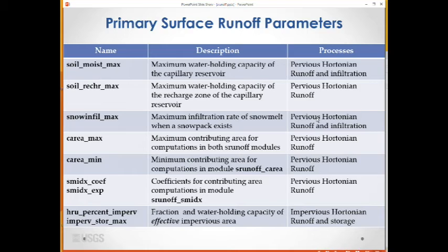Parking lots, roads, sidewalks, and building roofs can direct stormwater directly to the stream network via storm drains, gullies, and ditches. However, in some cases, this runoff may be directed to detention ponds that are used to promote soil infiltration and recharge. Runoff from some roads, driveways, sidewalks, patios, and roofs may drain to adjacent grassy or forested areas and infiltrate instead of flowing directly to the stream network. Additionally, stormwater on compacted soils and rock outcrops may drain directly to the stream network and/or infiltrate. There are many factors to determine the fraction and water holding capacities of impervious areas that is effective.